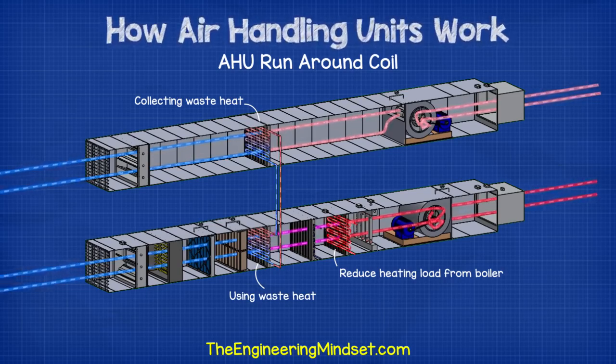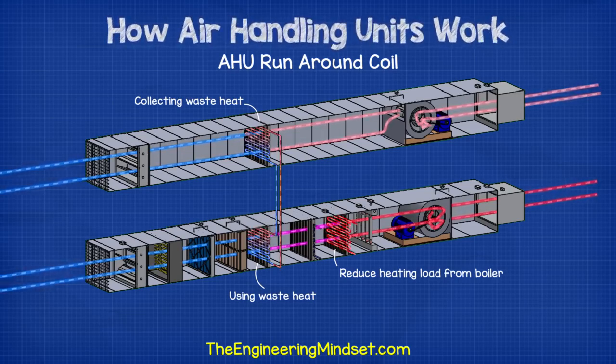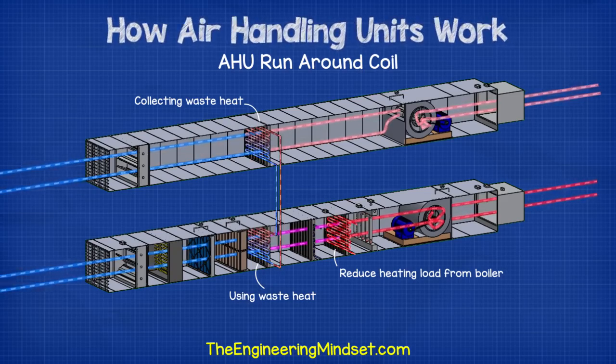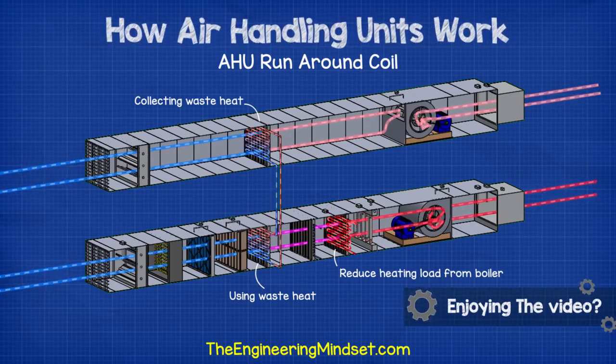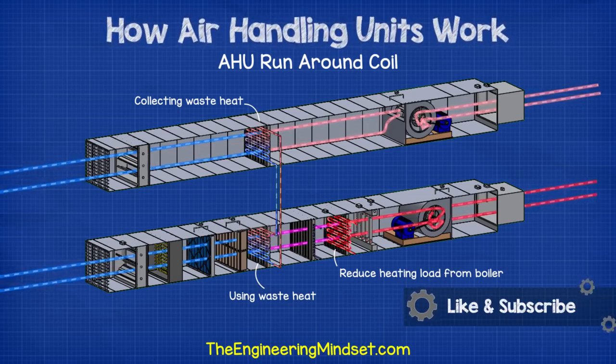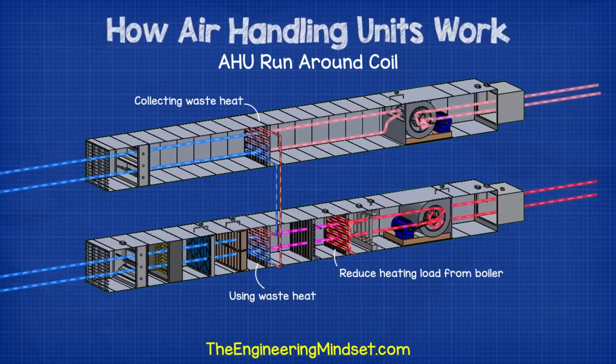This will reduce the heating demand on the heating coil when the outside air temperature is below the supply set point temperature and the return air temperature is higher than the set point. The heat would otherwise be wasted as it is simply rejected to atmosphere. As the pump will consume electricity, it is only cost effective to turn on if the energy saved is more than the pump will consume.